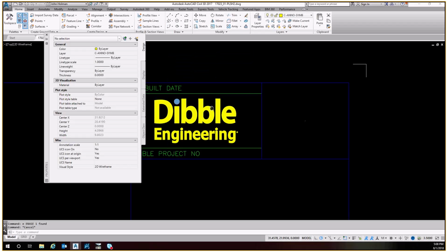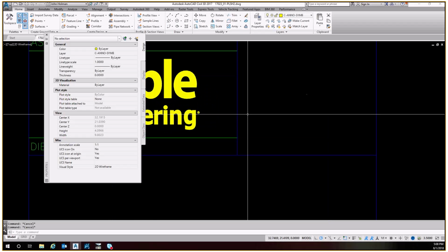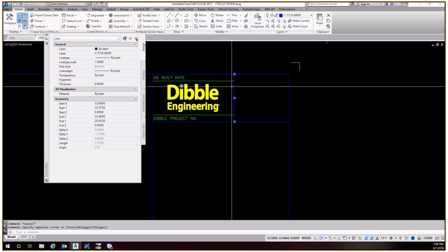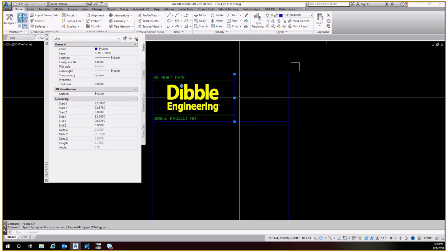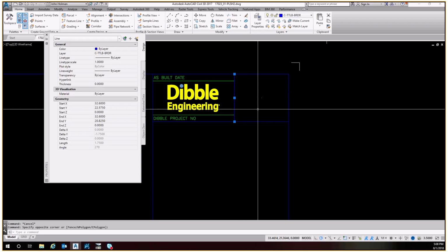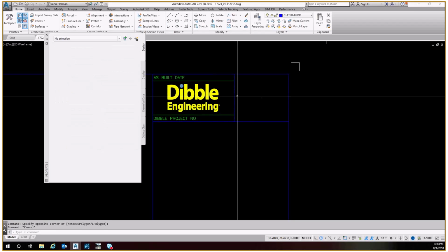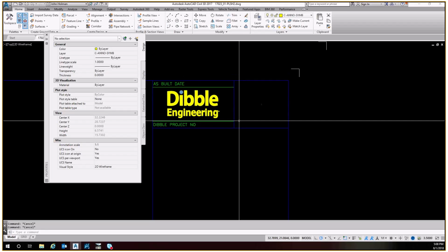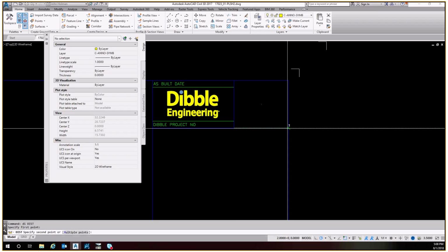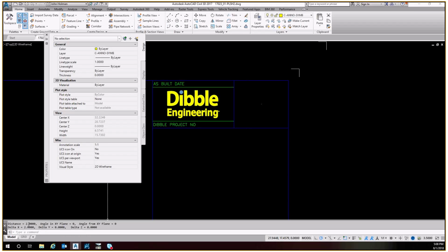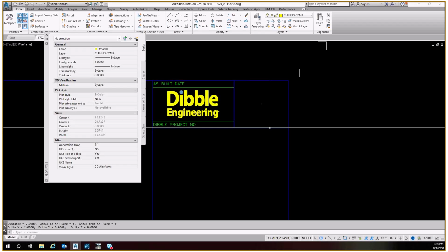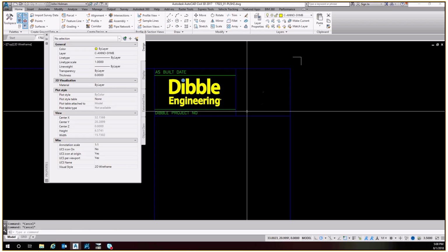top right first. The only other thing up here that I'd like to correct is that this blue line that controls how tall this seal block area is 1.75 inches tall. I'm looking at this delta Y here and the length of that line, which is 1.75. We want that area to be 2 by 2. So if I measure this distance horizontally, it is in fact 2 inches. I'm looking down here in my command line. So all we need to do is make it a little bit bigger vertically.